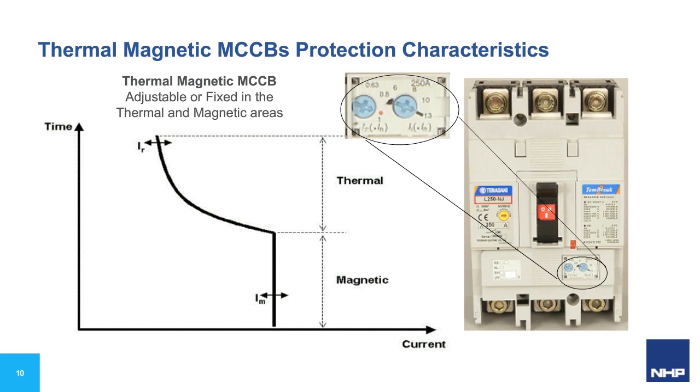Their wide tolerance band and susceptibility to setting drift due to ambient temperature conditions surrounding the breaker means tripping time may vary greatly. Thermal magnetic circuit breakers are best suited as the final distribution breaker upstream of miniature circuit breakers and RCBOs.